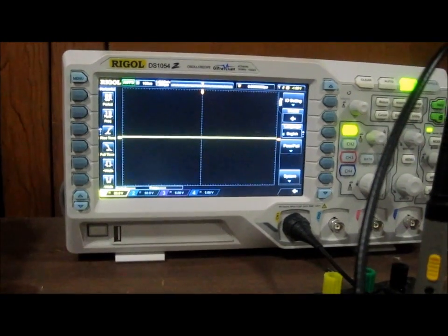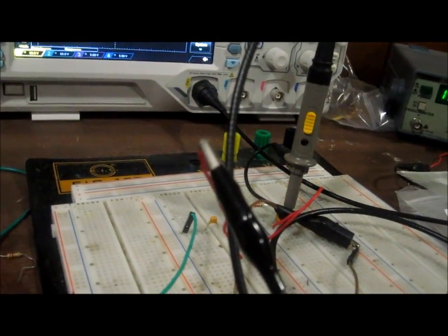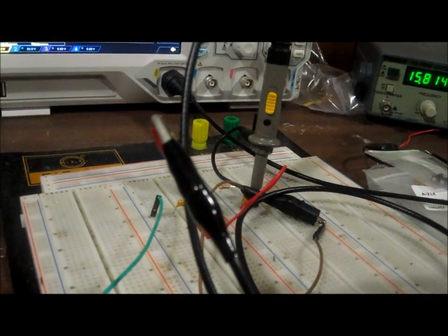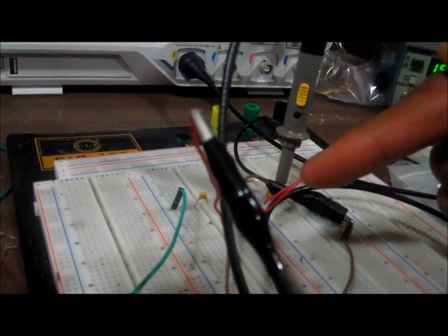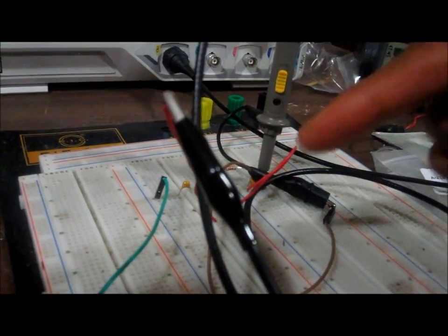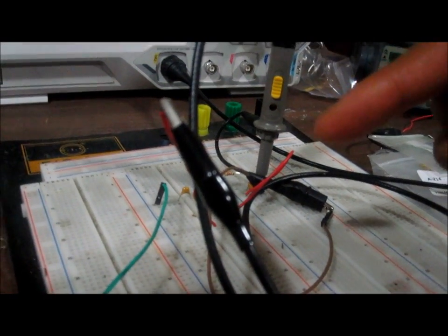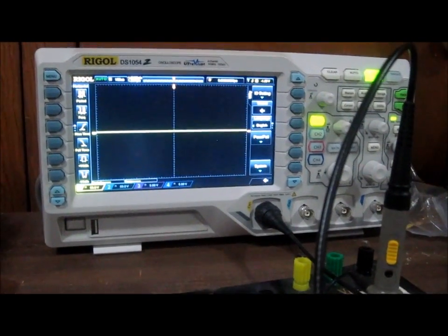So this is how a bandpass filter circuit works. You can design the bandpass filter so it has any lower cutoff frequency point or upper cutoff frequency point, and you can adjust this by changing the values of the resistors and the capacitors in the low pass filter or the high pass filter. And this is how a bandpass filter circuit works.